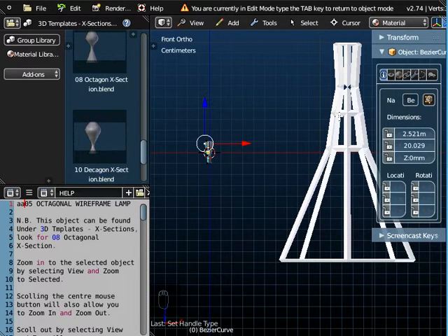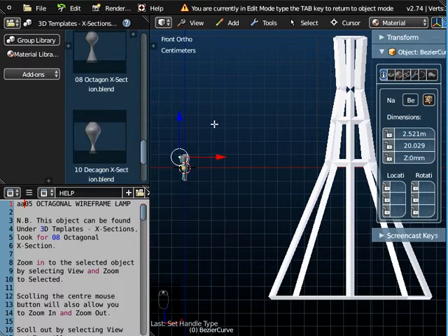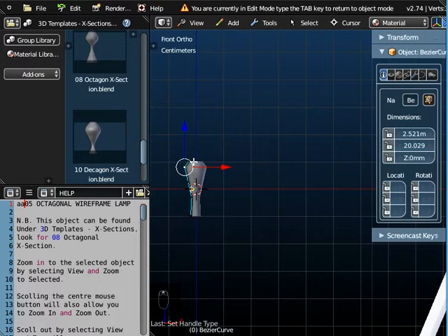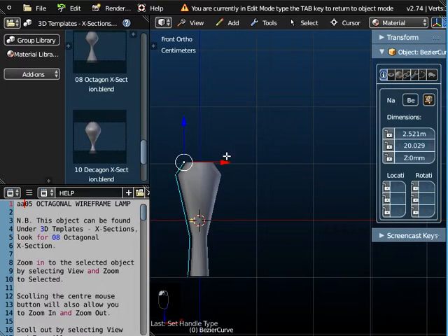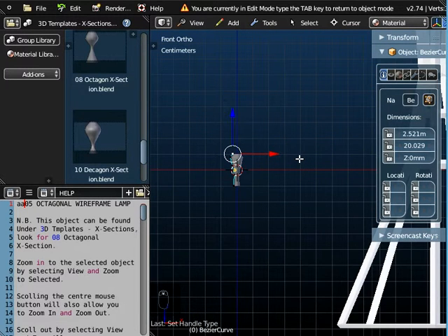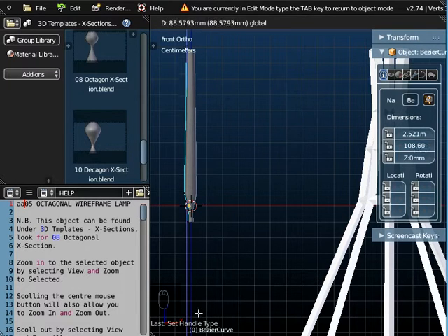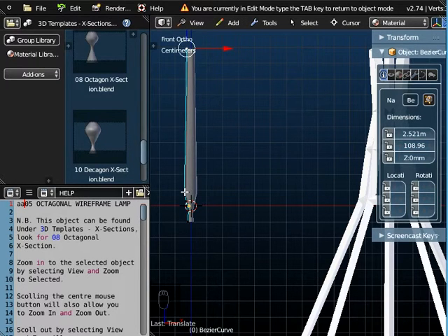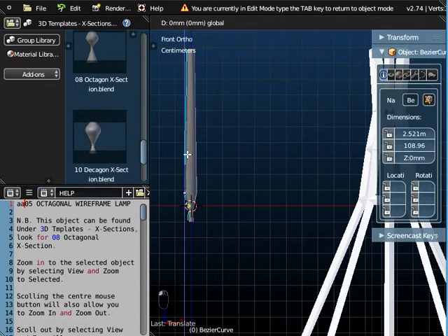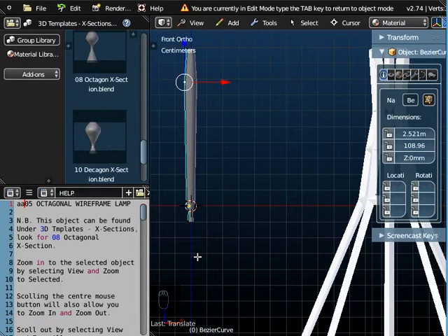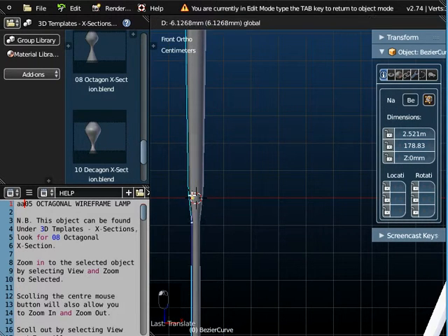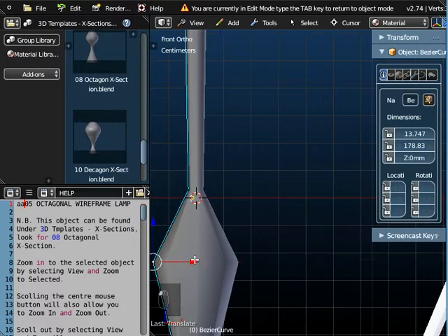We're going to enlarge it and make it look like this wireframe over here. So I'm going to have to keep zooming in and out, I should think, to select these control points until we get the sizing roughly right. So I'm going to drag that one up there. That's the top control point. The second control point, I'm just going to drag it up. The one at the bottom, I'm going to drag it right down. And I'm just going to move this one down and move it out a little bit.